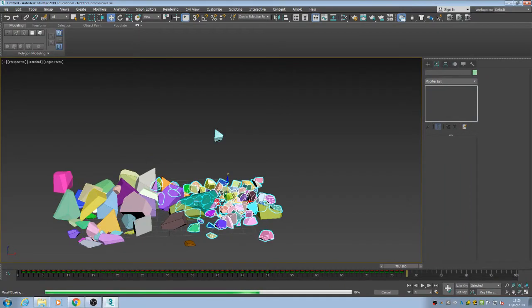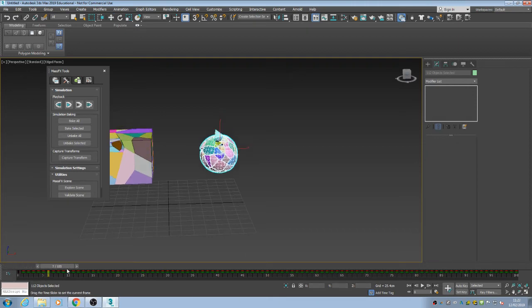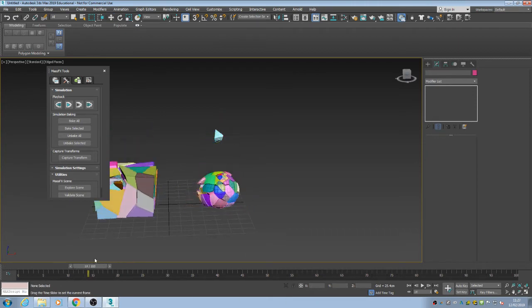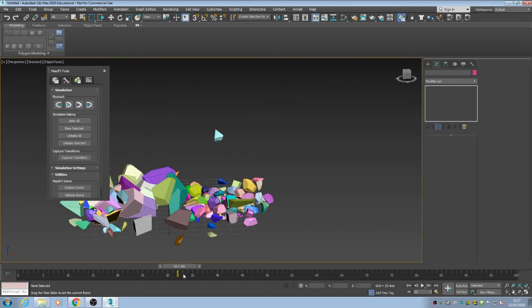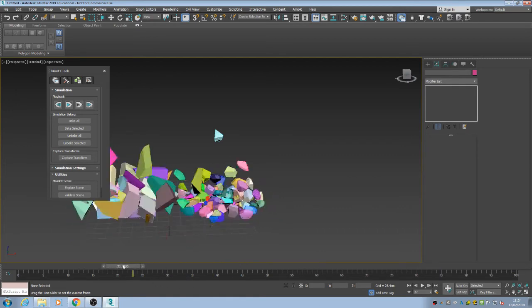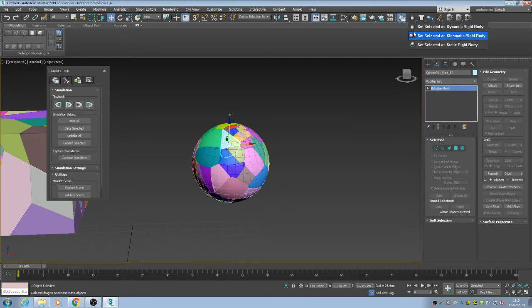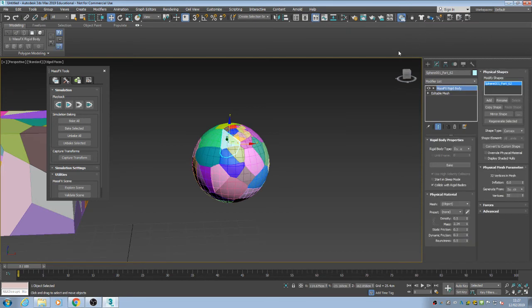And you can see the other objects here with the MassFX on actually interact with the circle. So let's deselect that. You can see how it's pushing all of the smaller pieces out of the way, which is very nice. And let's mess around with this one now. So let's put a MassFX dynamic on it. But what I want to do is, over in here we have the options. We can say its density, its mass, its friction, how much it bounces. Let's put the bounce to 1. Actually, let's put a balloon on here.